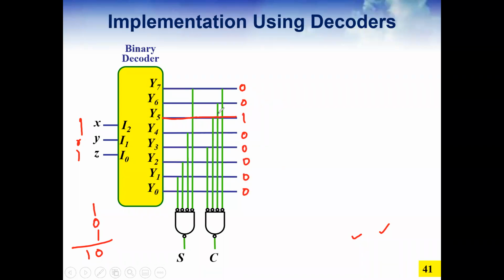You check now, because this is connected here. Because of this inversion, this value will be 0 here, and the rest are going to be 1 because they are inverting. So for this AND gate, what is the operation? Invert and then invert, so this is the AND operation. So 0 will multiply by 1, 1, 1, so output will be 0. And then there is a bubble inversion. So what will be the value of C now? 1. 1.